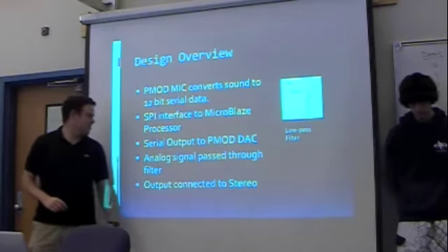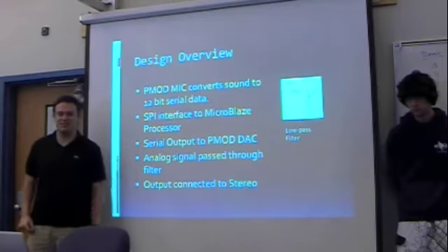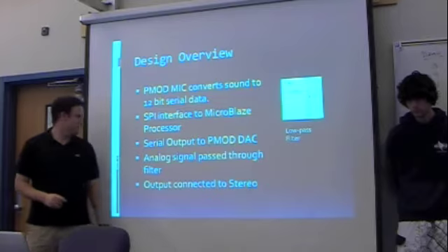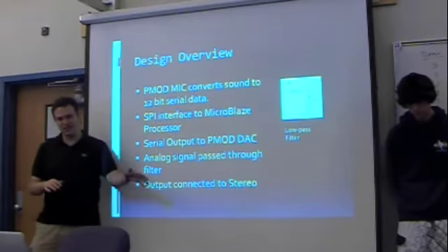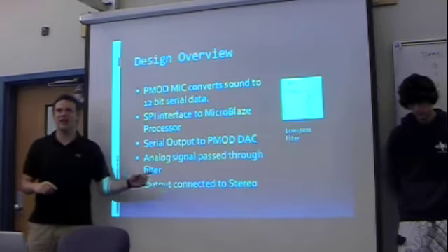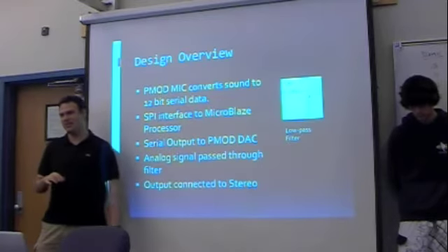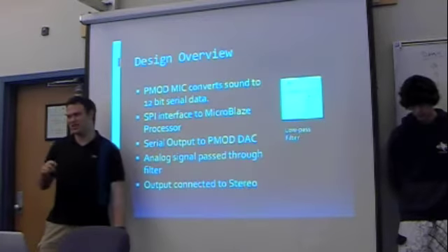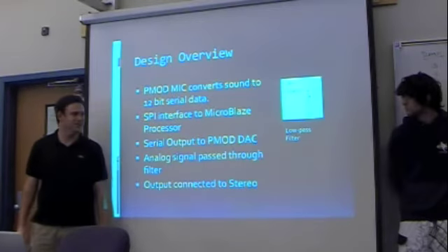Otherwise the signals won't come out fast enough. One of the ways to make the signal more stable was we average every 10 samples together and output it, which got rid of a lot of the static, but it's still pretty bad so far.